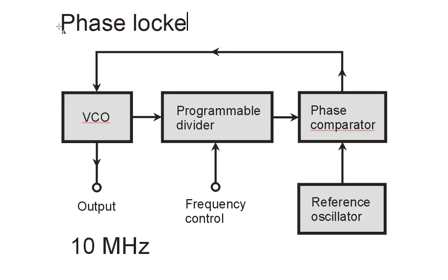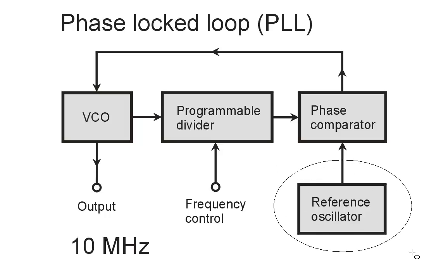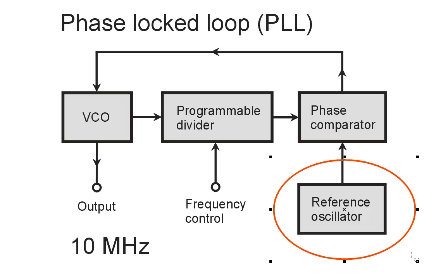The phase-locked loop, otherwise known as a PLL frequency synthesizer. And that is choice A, and according to this block diagram, you can see that this type of circuit locks the signal in phase and therefore to the frequency of a reference oscillator, which can be a Reinhardt's or a Pierce or some other crystal-controlled oscillator.